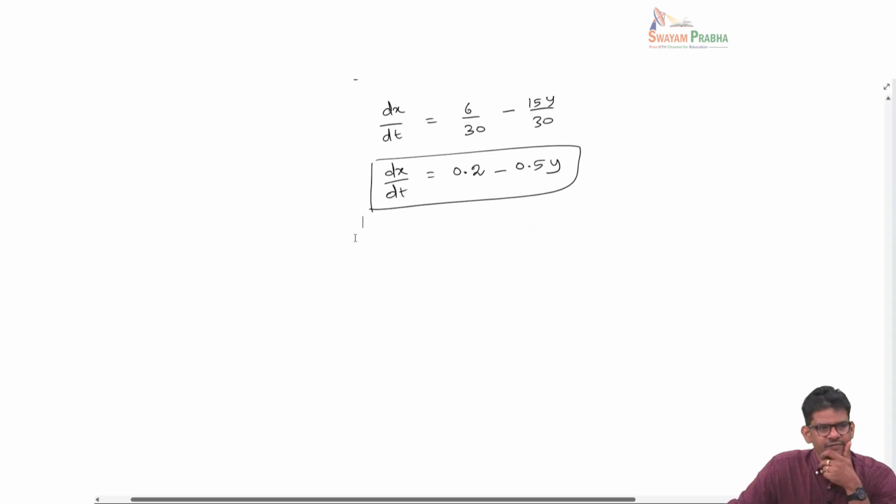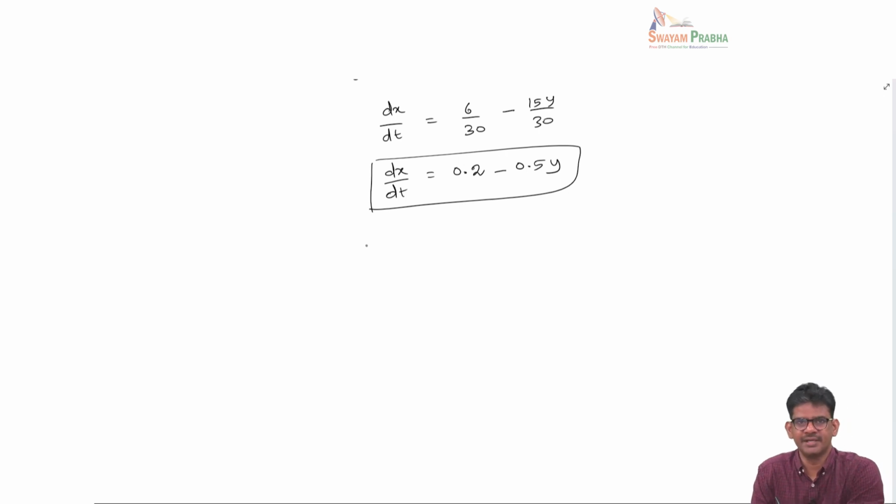So this equation tells me how the composition in the liquid is changing with time because of this operation that we are talking about. And that depends on the composition of the vapor Y. So this is where the VLE data will have to be used to couple the two. But here in this problem, the relative volatility is constant.